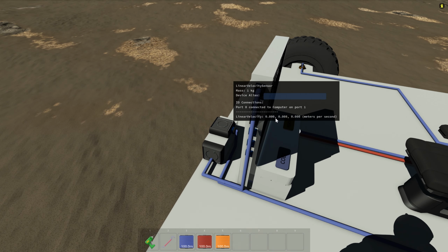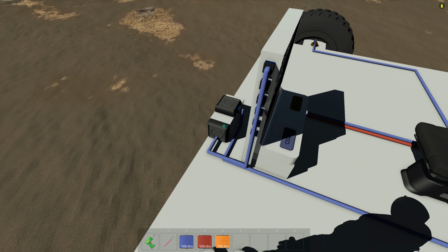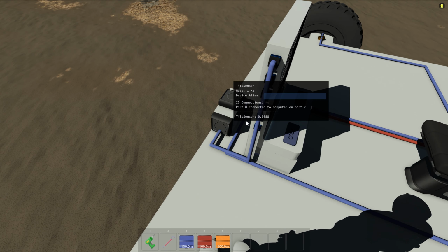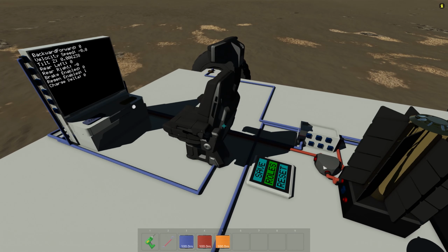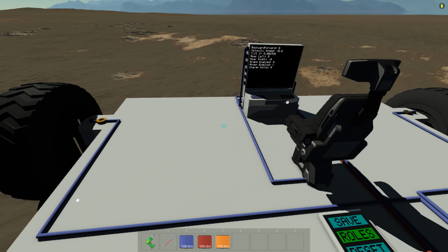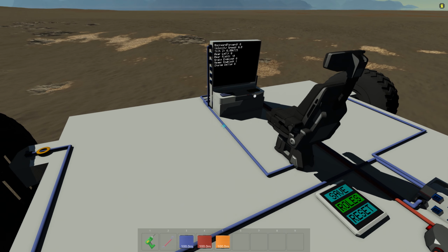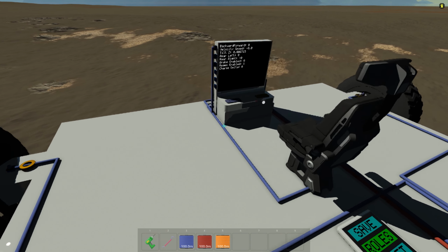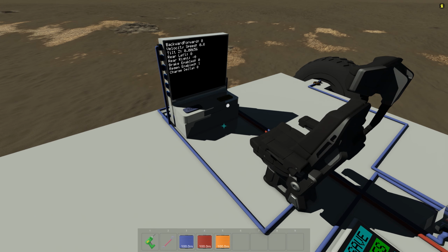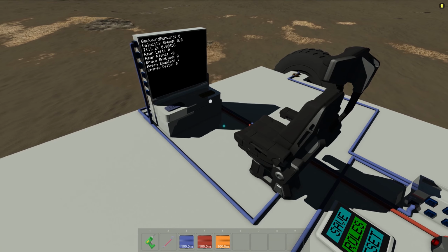In the front here, we have our velocity sensor that gives us our speed indication. We only pull for speed, which is our z-axis, and then we have tilt, and that's just for display right now, and we can see the tilt as we do a little wheelies here. Now, this first part 1 only supports going forward and backwards, braking, and automatic regen when we're not accelerating. And anytime I say acceleration, that means either positive or negative.